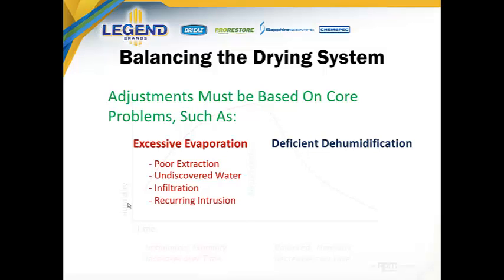Let's say the reason we have really high humidity is because the water source has not been stopped, or there were multiple sources. Say we had a really hard winter and it's December. Some high winds along with freezing temperatures have caused a bunch of frozen pipes in a facility. We did find the broken pipe, fixed it, turned the water back on, and began the drying process, and lo and behold, the pipe was broken in 4 places, not 1. Adding a dehumidifier does not fix that, right? So these are lots of causes of a substantial humidity spike where adding a dehumidifier does nothing but cover up the symptom. It doesn't actually address the problem.